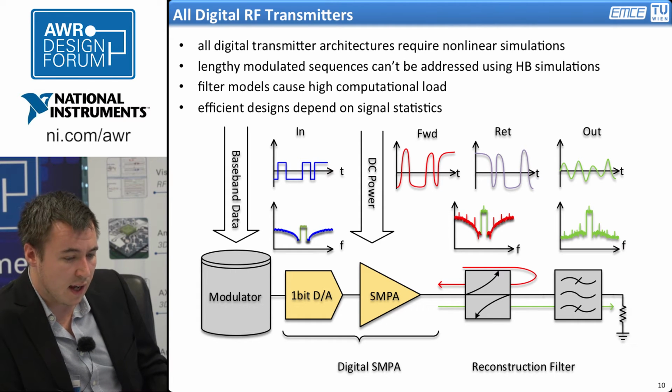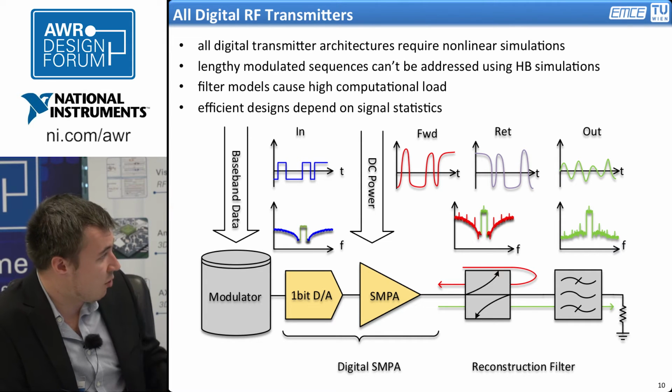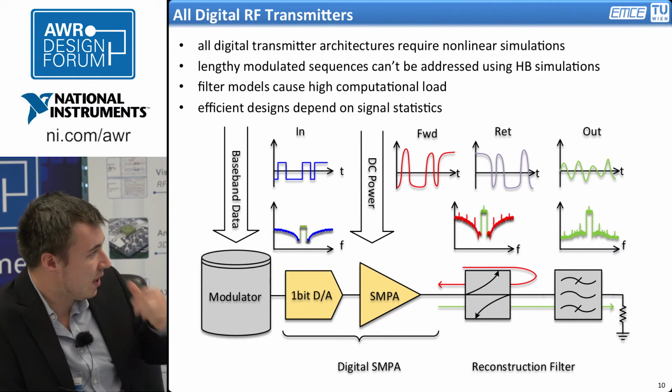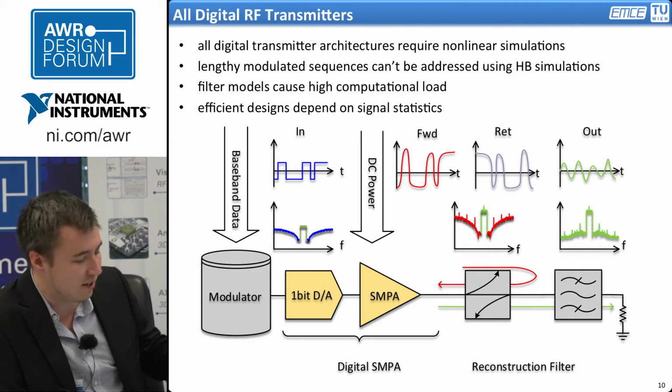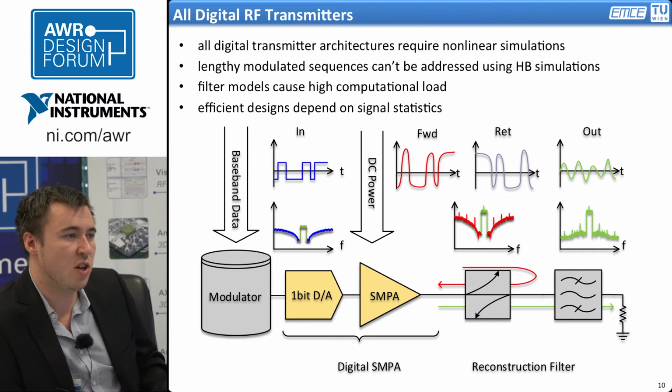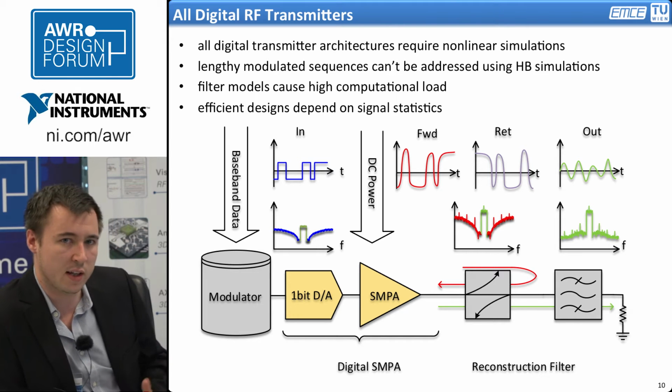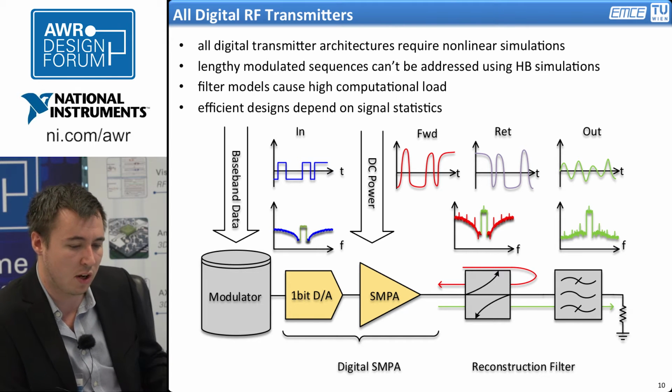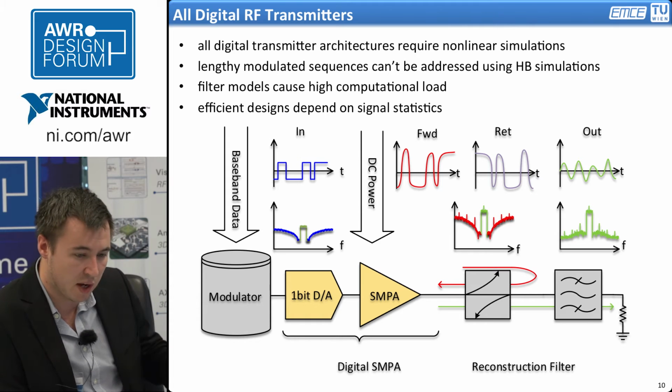And on the other hand, the reflective output filter, which needs to have a high Q in order to be very selective, causes some memory effects in the circuit, which are a somewhat tricky thing to handle. Of course, filter models could be an approach to do so. On the other hand, we're just shifting the problem from solving the circuit simulations to identifying the proper filter model. So that's not really solving the problem. It's just pain conservation.